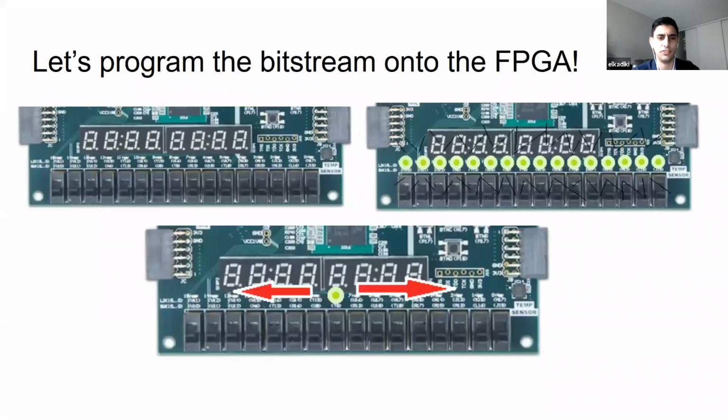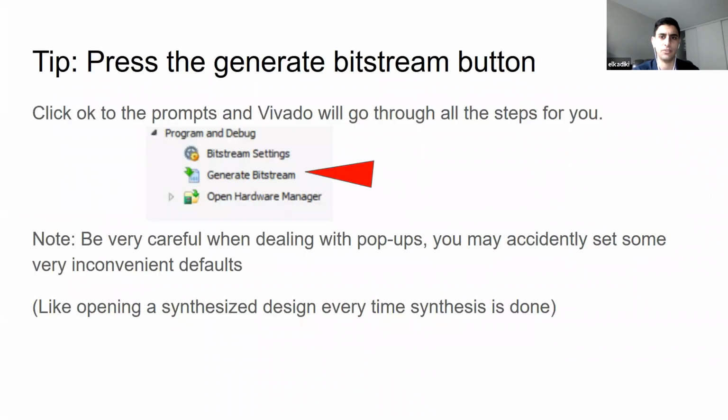Yeah, I don't think any of the FPGAs are beyond nanoseconds right now. Even the most expensive ones are still on the nanosecond time scale. I think the only part that's actually in picoseconds is the transition time, whereas the whole clock cycle is usually defined in nanoseconds. One thing that's interesting to note is with FPGAs, the more money you spend, you don't really get a faster FPGA, you just get more space. That's essentially what you're paying for.